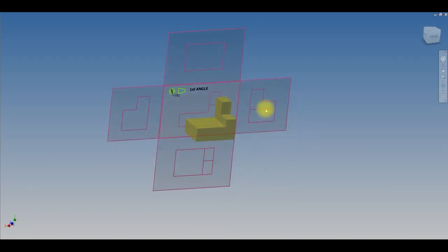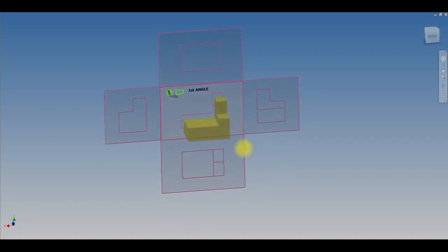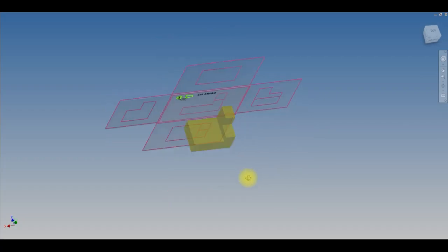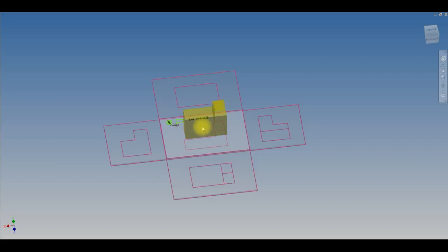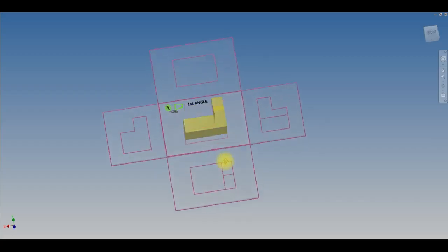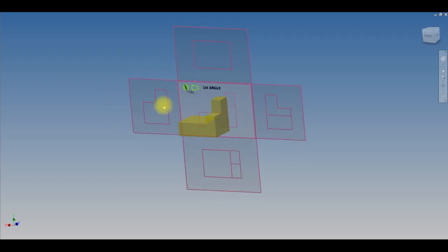You'll notice here that this line represents this line here. On the bottom view, this line represents this line, and this line here could be a combination of the top level or this bottom level line. But what's shown on the bottom view is what you see from the top. The top view is what you see from the bottom. It's projected upwards. This one here, what's seen from this side is projected onto that panel, and vice versa, what's seen on this side is projected onto that panel.